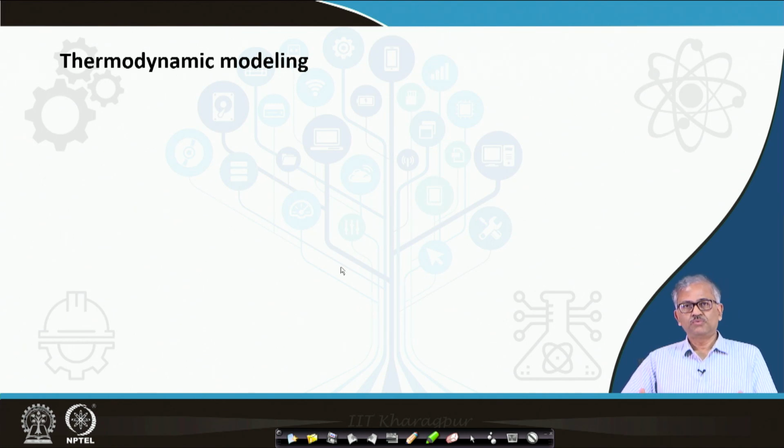Sometimes it has been found that a multi-zone thermodynamic model works better. That means we divide the whole calculation domain into a number of reactors and connect them by input-output flow, one reactor to another, and then it moves a little closer to the real situation.